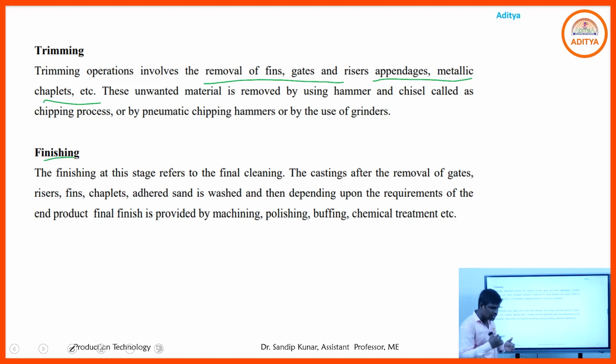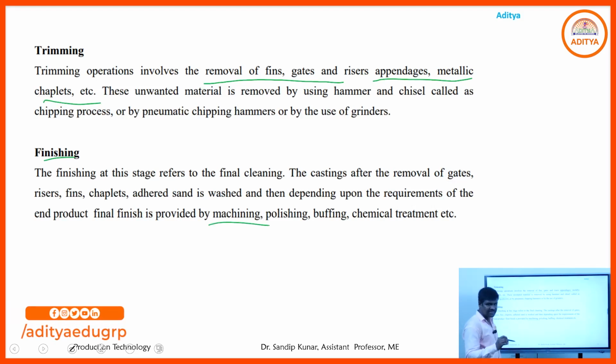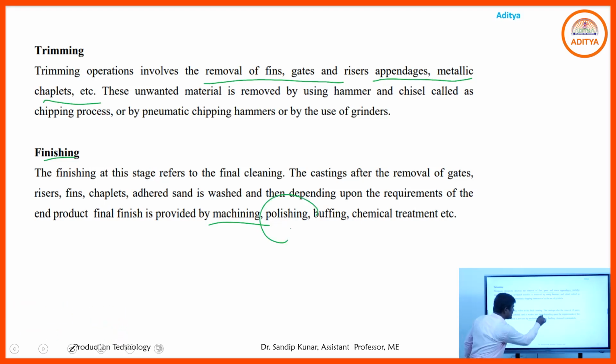Sometimes some sand will stick to that particular product, and that we also remove by using some cleaning process, using a brush. Using that brush we remove those impurities and debris. We also use conventional machining processes to remove some extra parts, and there is a polishing process, a buffing process, and sometimes a chemical treatment to remove extra, unwanted parts. Okay, that is the finishing operation.